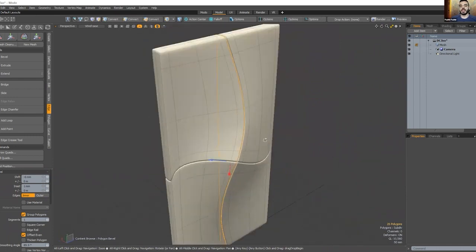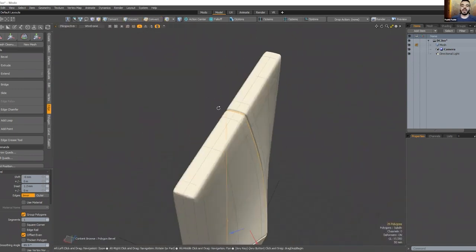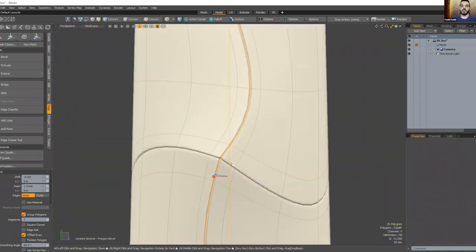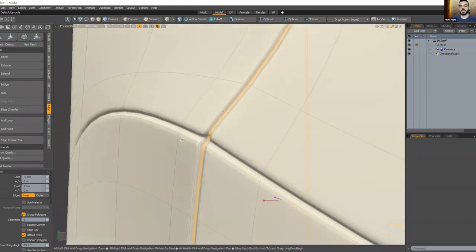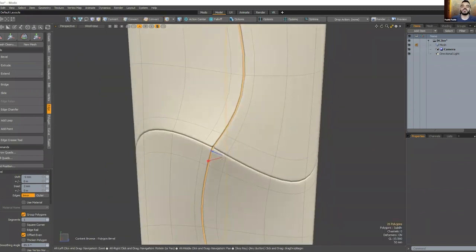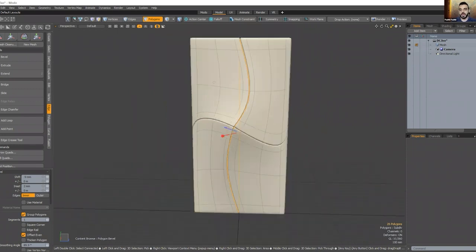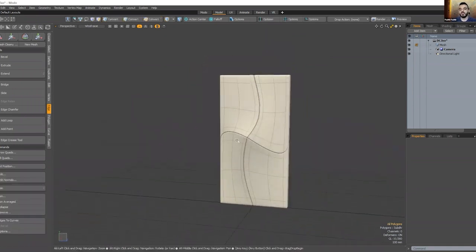So now I know for sure that there are 3 different ways I can do this. And actually, I even have the luxury to delete these polygons in between and really just bridge everything. But for now, I'll do it later. The reason why I would delete these seams is so that I can have separate panels that are ready to be printed or CNC'd or whatever. So now I know that this wall is going to be made out of 4 different panels. And I have a seam in between.